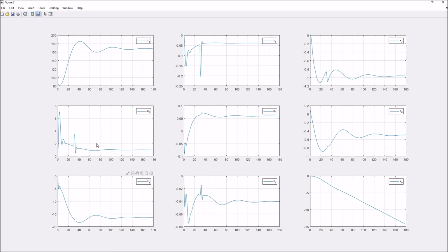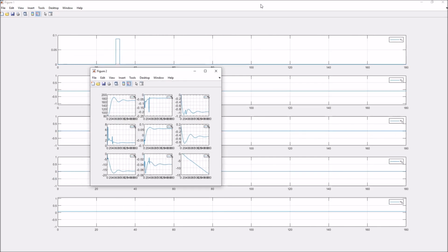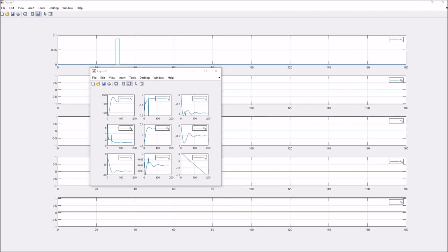Look, stuff is going kind of wrong. Although, surprisingly, this is not too horribly wrong. It does almost look like we actually end up at a steady state. Wow, I'm actually shocked. I guess at this low throttle setting, it looks like we are actually flying stably. Although, if you look at psi, it looks like we're just in a turn, right? We are in a counterclockwise westerly turn, we're basically going around in circles at this point. But again, that makes sense. We've got one engine on and one engine off. So this is great, I think. I think we're at a really good spot.